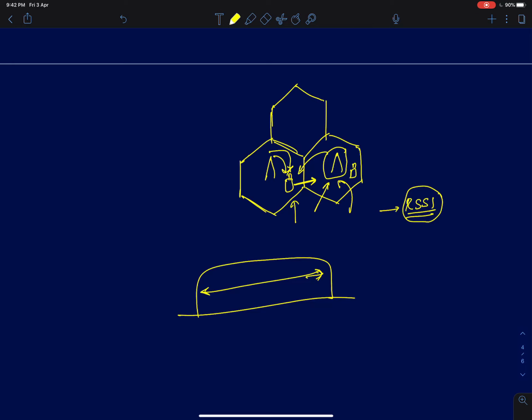But CDMA has a very interesting advantage here, because it's not going to use up any extra frequency. The code is not used by the other users in this cell because every code is unique. So it will transmit data using the same code as this tower is using. The frequency is the same to begin with, so that way we can ensure a very soft handoff. This was one of the big selling points for CDMA, because they wanted to show its superiority in every way possible as a digital communication system. Soft handoff was also a big selling point.